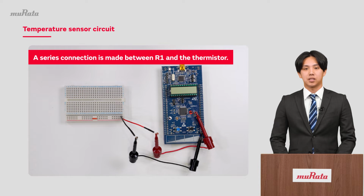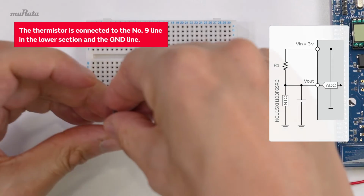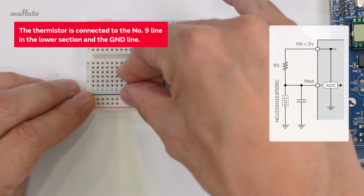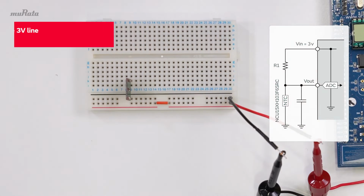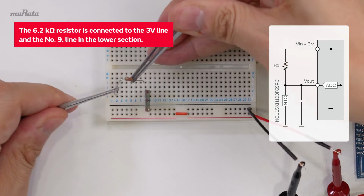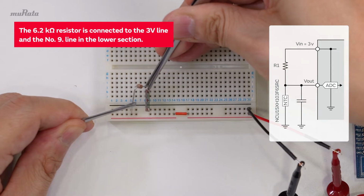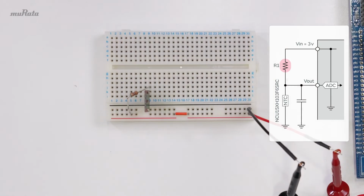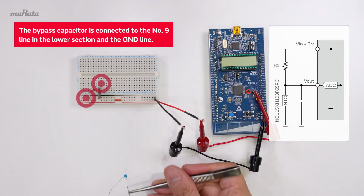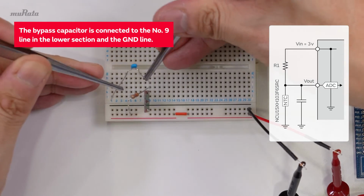Next, we will connect R1 and the thermistor in series. We connect the number 9 lower section line to the thermistor and the other end to the GND line. Then we connect the same number 9 lower section line to the 6.2 kΩ resistor and the other end to the 3V line. We connect the bypass capacitor between the number 9 lower section and GND lines.